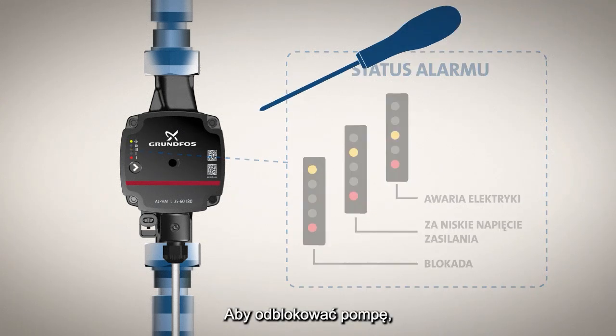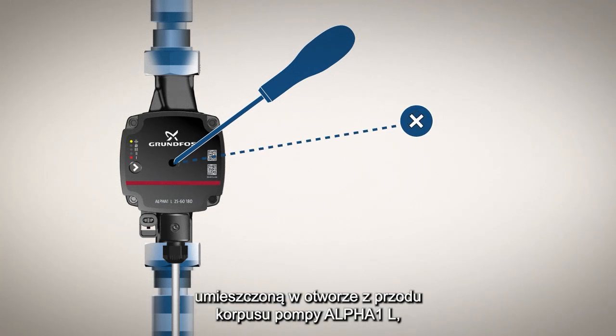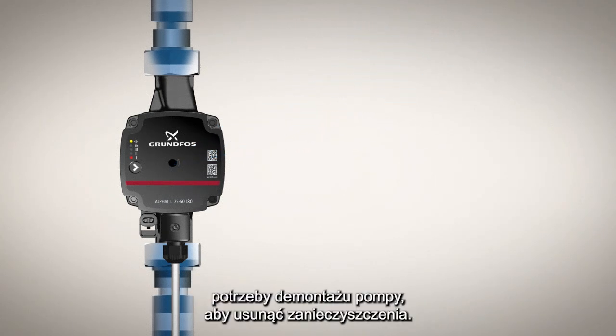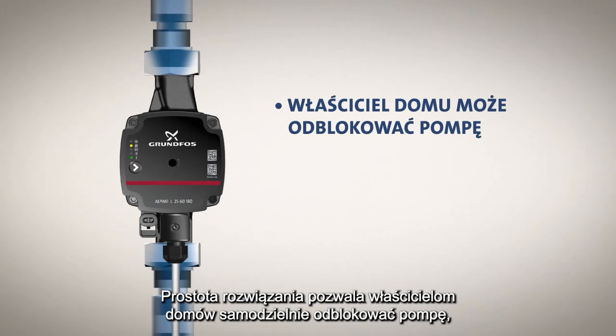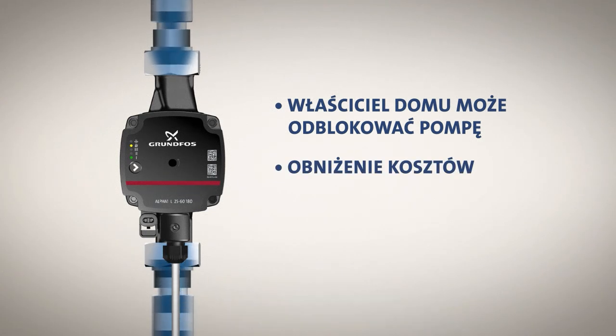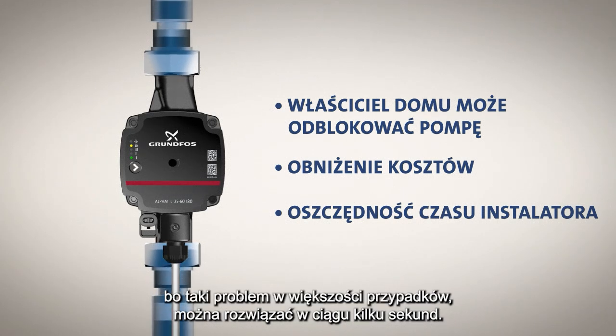To unblock the pump, simply press the deblocking screw placed on the front of the stator housing of the Alpha 1L with a screwdriver and twist it to loosen the rotor and make it free to rotate. Thus, there is no need to disassemble the pump to remove impurities. The simplicity of this allows the homeowner to unblock it himself, thereby saving him the cost of an installer visit, while also saving the installer's time with a problem that, in most cases, can be solved within seconds.